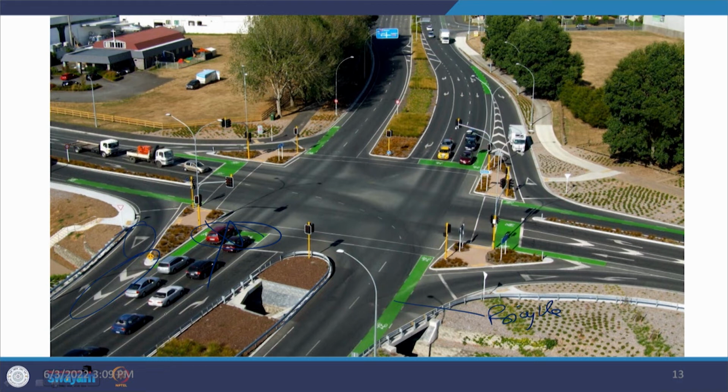Okay, so, the arrows which are specifying the directions in which the traffic can move, and the various types of channelizations which are there, which segregate, say, the through traffic and the turning traffic. So, all of those things have been done perfectly, and again in this type, you have a flaring also on this side, because there is a lot of traffic which probably is going in the through direction or the straight direction, as well as there is a right turning traffic and the left turning traffic. So, they have been done perfectly.